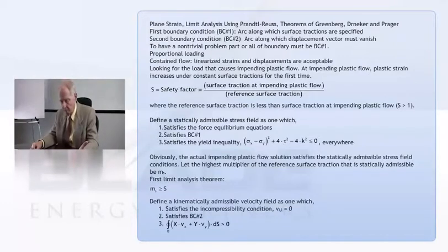And there's a third step here, given at the bottom of the page, which is simply saying that the boundary loads have to do positive work on the velocity field that you guessed. If it doesn't, change the sign. And if it doesn't do any work, if it's 0, then you're really missing the whole point of the problem. So you ought to go and reconsider what you've done. Okay. Now, if you get that far and you have your velocity field, then you calculate on the next slide.